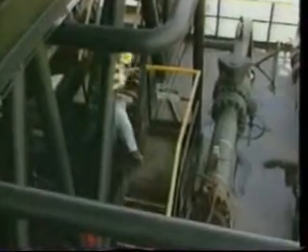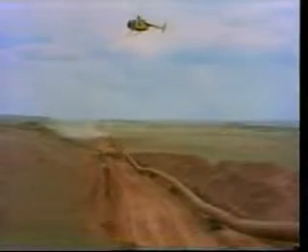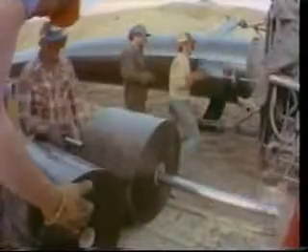One commonly recommended practice involves running a scraper or pig, which is slightly smaller than the line ID, ahead of the water. This tests the line for obstructions or other abnormalities that might adversely affect flow line performance. Other methods of flow line inspection are discussed in your manual. Flow line performance can be adversely affected by several things, among them thermal and electrochemical problems. Thermal insulation can be applied to prevent possible heat transfer when transporting hot or cold fluids.